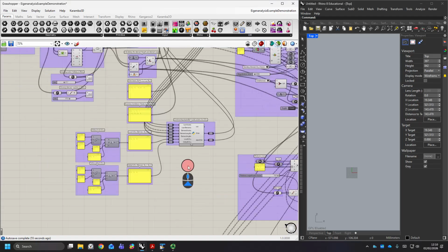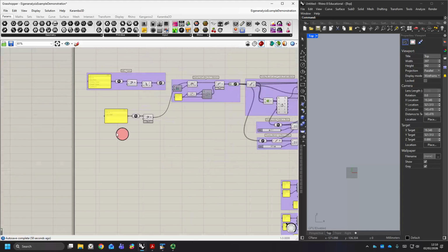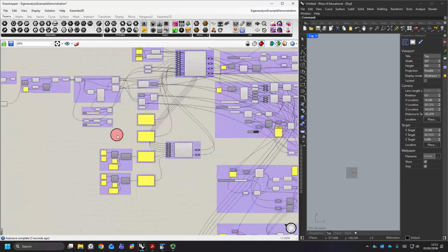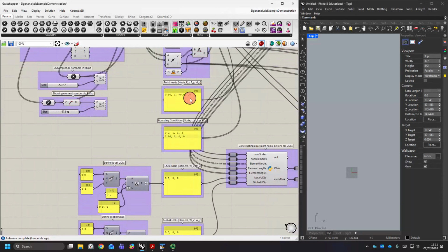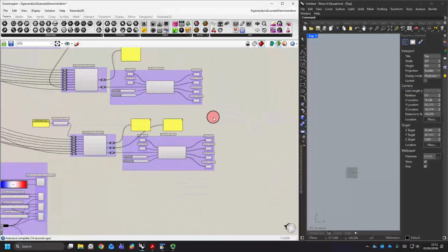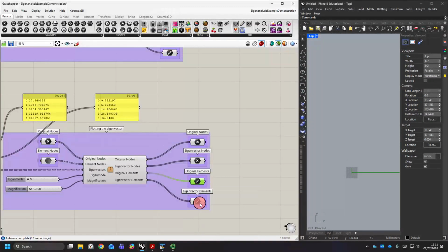If we did just want to check some values, for example, might go back here. So I could just turn this into either a simply supported beam or a cantilever. So if we turn it back into simply supported beam, remembering it really doesn't matter what the loading is. So in this case, we'll have a cantilever when we're doing our frequency analysis, that is. So here, again, we have the modes that we would expect. We can just cycle through them quite easily.